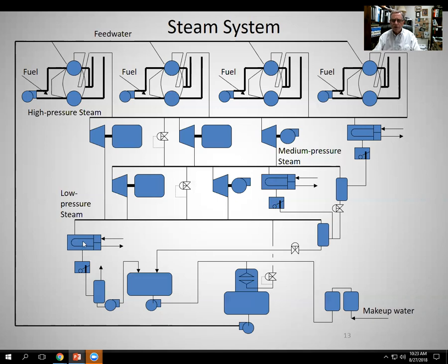And then we've got another heat exchanger over here utilizing low pressure steam, another fluid in and out, another trap, atmospheric pressure flash tank, losing some steam to atmosphere. All the condensate is going to flow into this and then get pumped back over to the deaerator where the makeup water comes in. So hopefully you're starting to get a little bit of a feel for at least how things flow through the system.